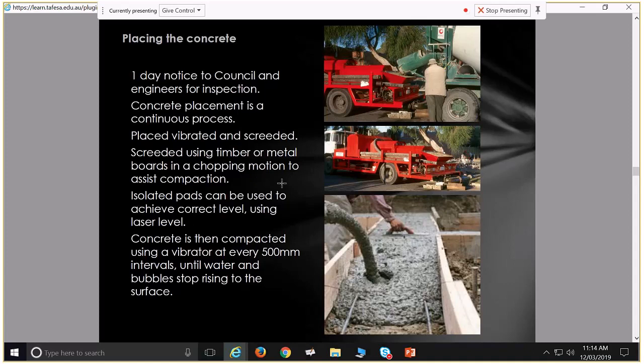So for those really deep beams, you cast the lower section first, and you keep a rough top to that, a top to that concrete that can easily be bonded with the second layer of concrete. But except for that scenario, you always want it to be a continuous pour.